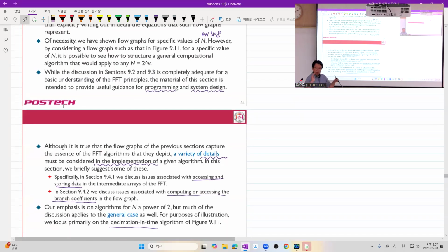Because in order to compute the FFT, you need to form a vector. If you directly apply, for example, the decimation in time or decimation in frequency algorithm, you need to store these samples, especially when the number of points is large. At that time, large means 4096. It was large enough at that time. You have to have around 4K memory cells to store those input vectors alone.